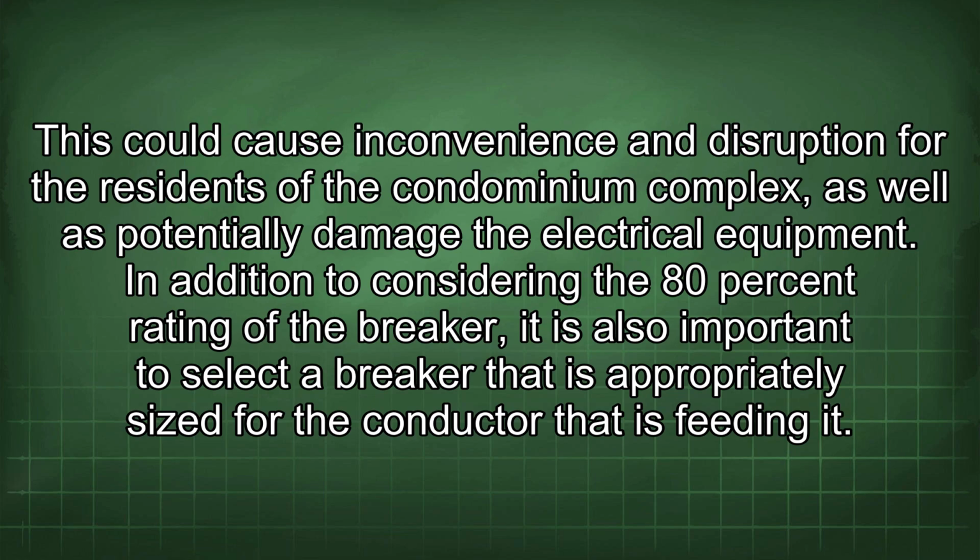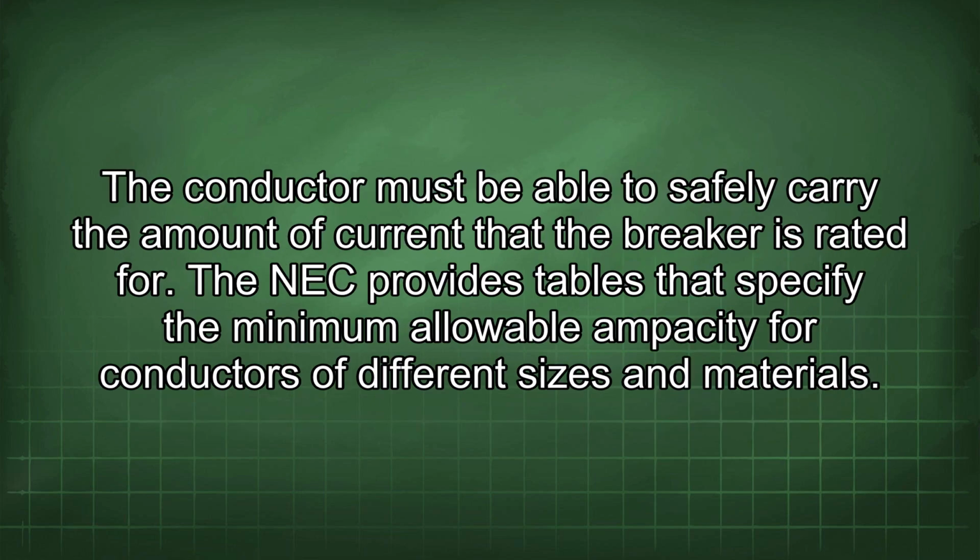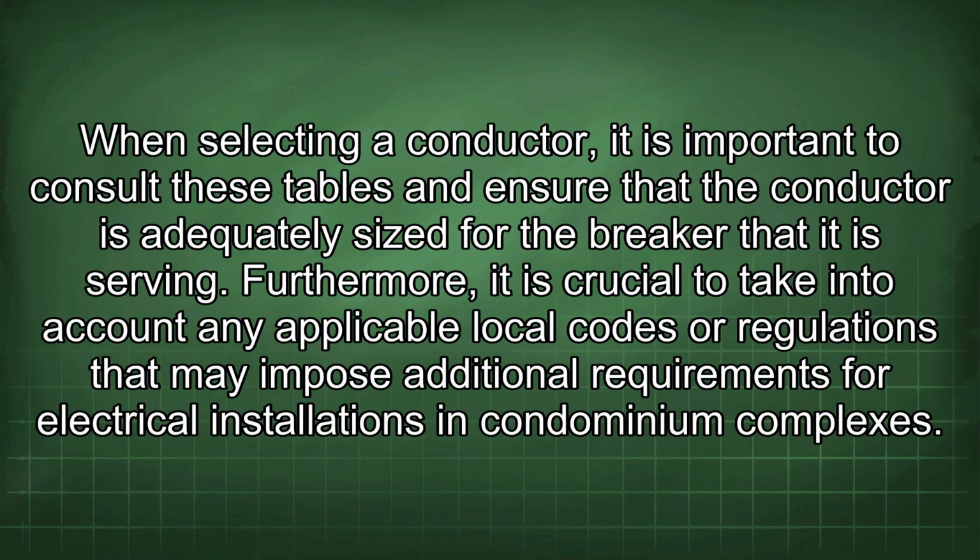breaker that is appropriately sized for the conductor that is feeding it. The conductor must be able to safely carry the amount of current that the breaker is rated for. The NEC provides tables that specify the minimum allowable ampacity for conductors of different sizes and materials. When selecting a conductor, it is important to consult these tables and ensure that the conductor is adequately sized for the breaker that it is serving.